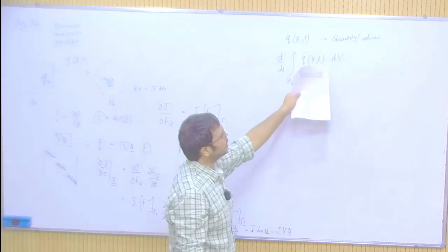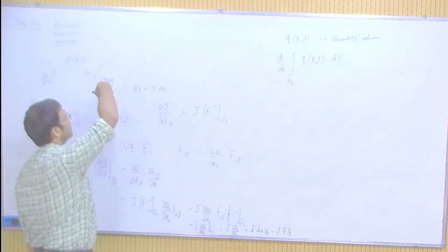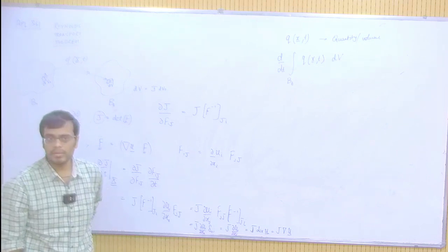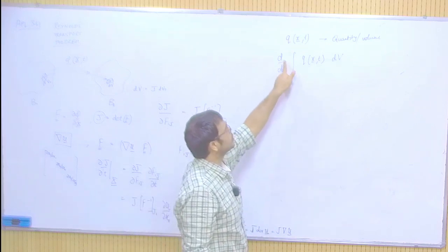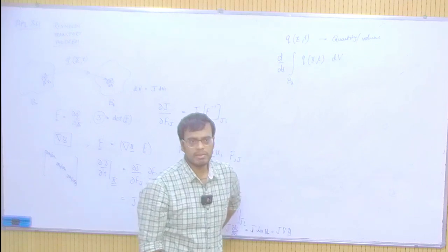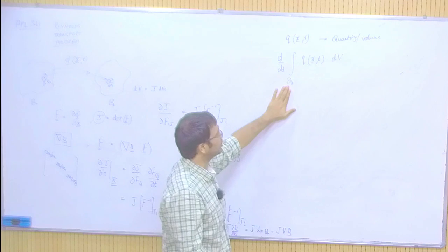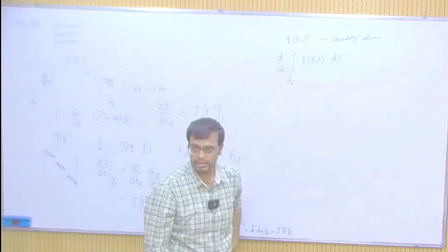And the integral of q dv over B of t is the total q that exists in the deformed configuration. I want to know its rate of change. Now, those of you who know Leibniz rule would immediately say that you cannot just bring this time derivative inside, because the shape of this blob would be changing. So the domain of the integration is changing in time. So you cannot just bring this derivative inside.